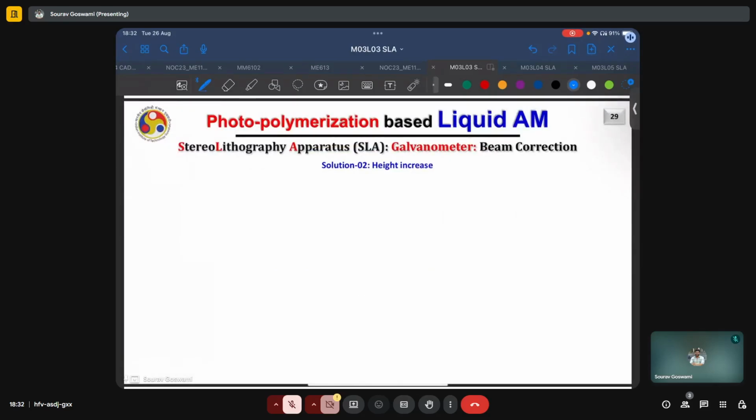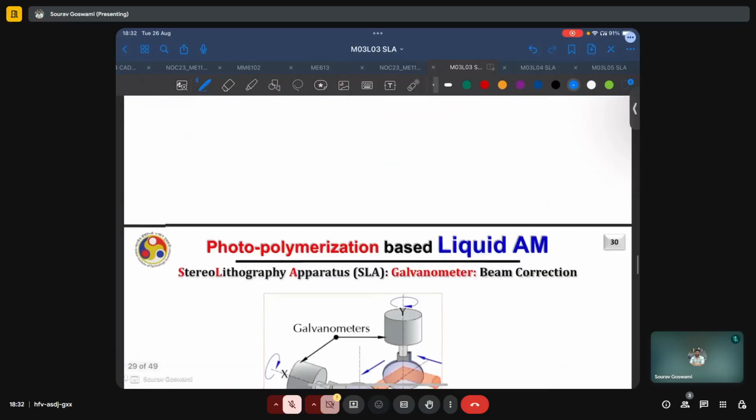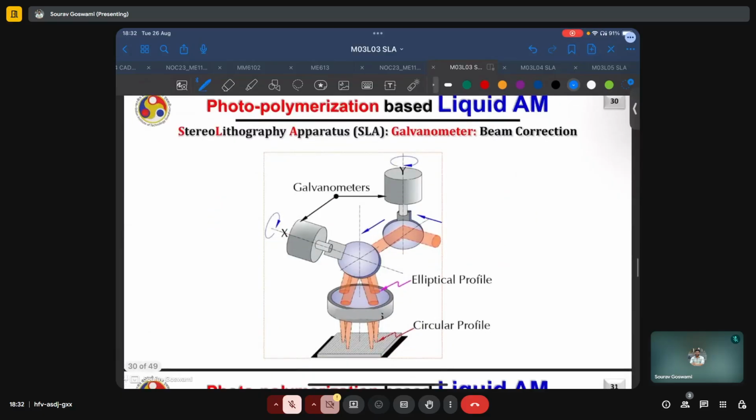That is, we can have the laser spot always on the printing plane without any additional optics. And here we have a schematic representation where you have a pair of galvanometers and it is passed through some f theta or eccentric f theta lenses. And here you are also splitting the beam so that you have multiple spots falling on the surface.